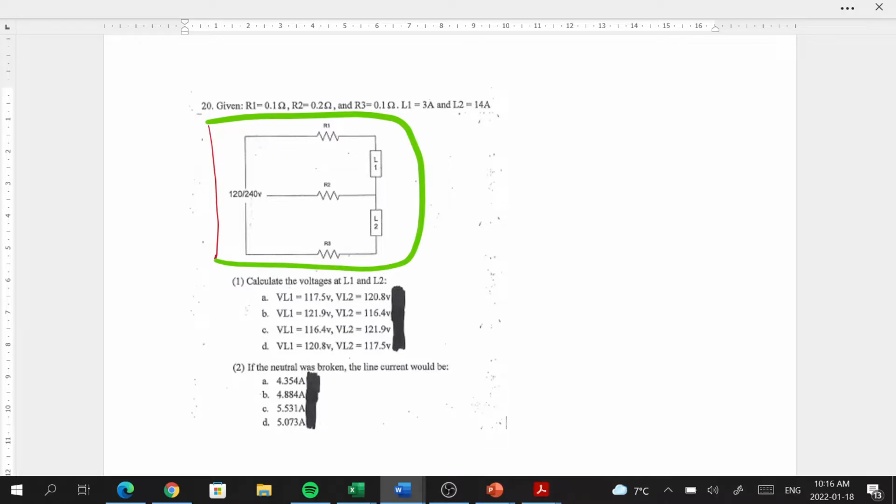As you know, a three-wire circuit consists of a line 1, a neutral, and a line 2. Between the neutral and line 1, you're going to have 120 volts, and between line 2 and neutral, negative 120 volts. And between line 1 and line 2 you're going to have 240 volts. This is the system that we use in all residential housing so that we have access to two different voltages, and it's also safer. We've got a grounded neutral, and the benefits are huge.